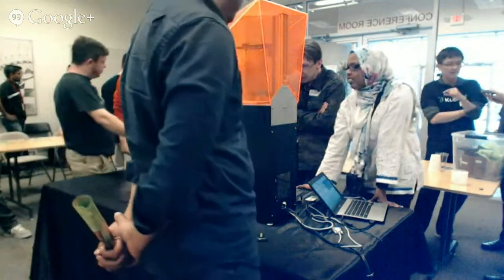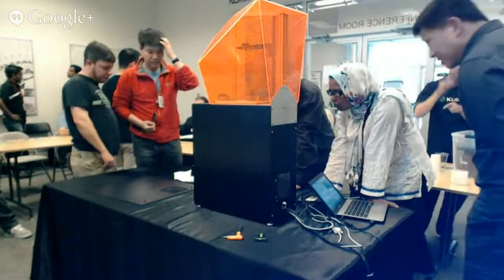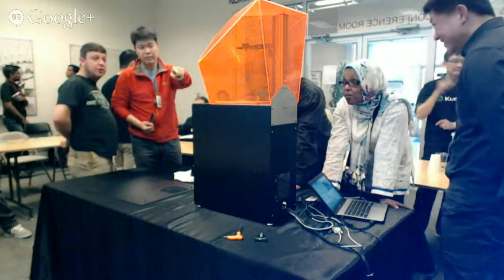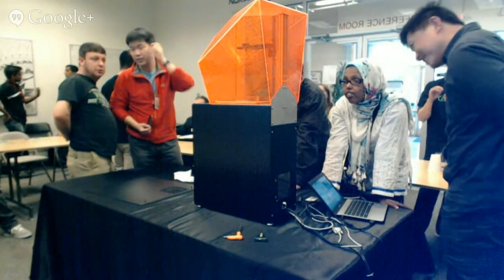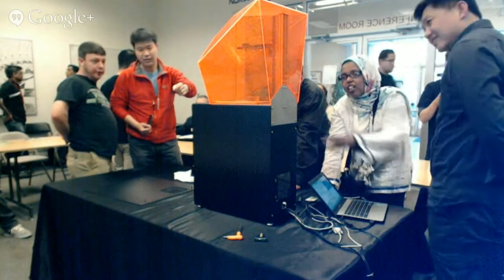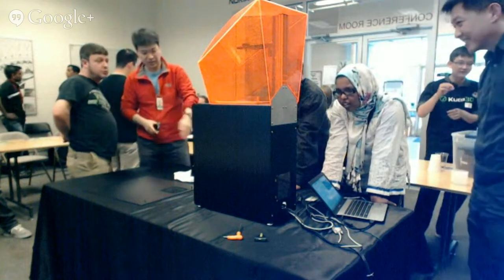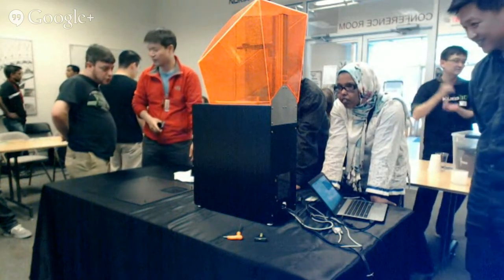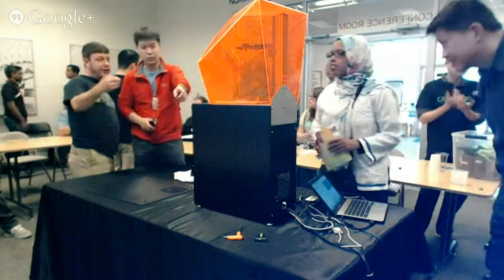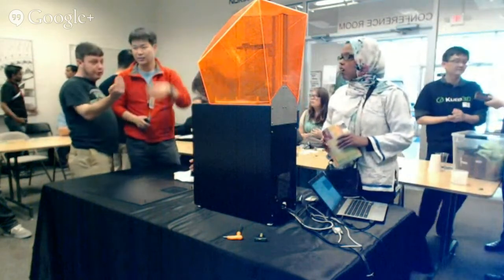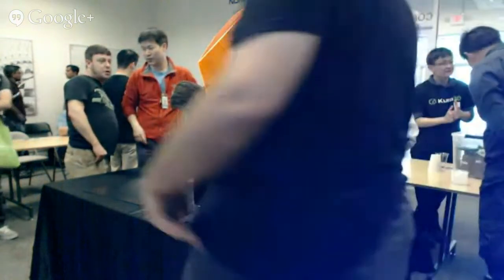The back part is Teflon, and resin sticks much better to other resin than Teflon by several orders of magnitude. So even if the surface area from one layer to the next gets bigger, you can often survive that because the resin still sticks better to the previous layer of cured resin than it does to Teflon, because Teflon is pretty non-sticky stuff.